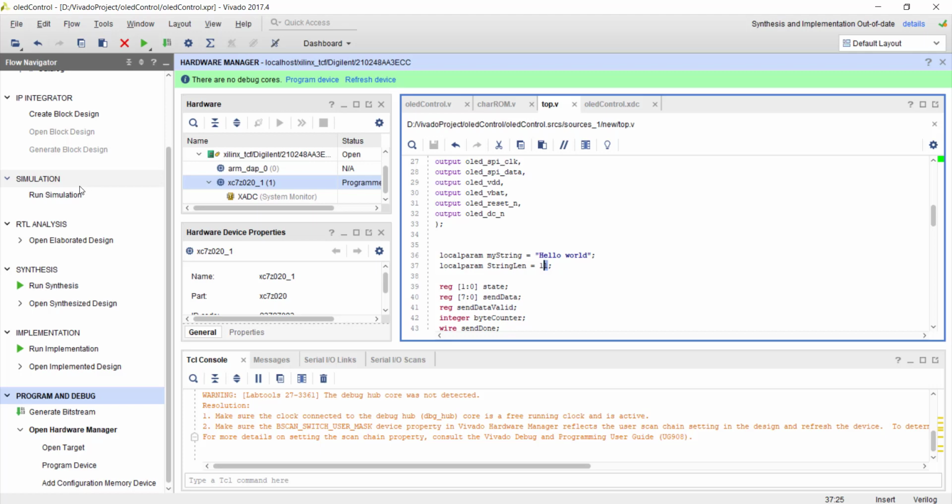So one thing that we can do is convert this OLED controller into an IP format, and we may interface this IP with the ARM processor through the AXI interface. Then I can use software to send the required string to the OLED controller. In that way, through hardware software co-design, I might be able to have a better design, with more flexibility compared to pure hardware implementation.